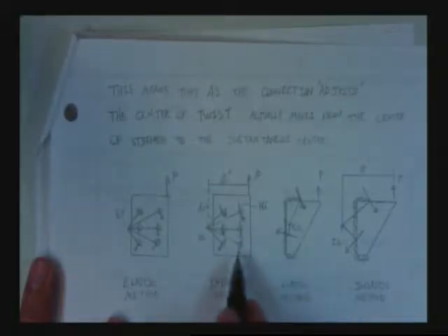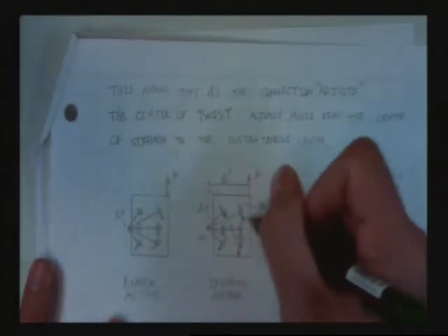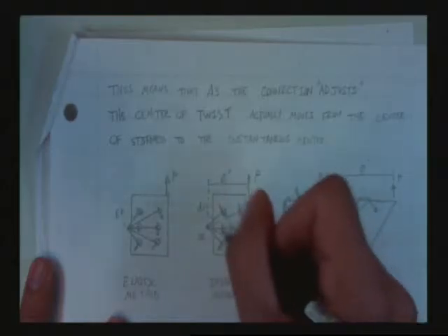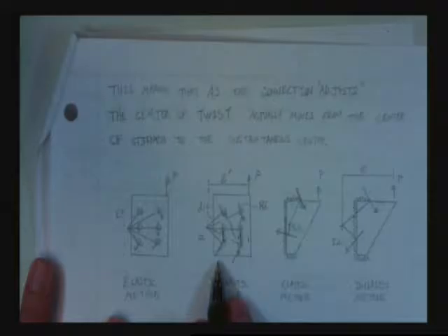We'll talk more about that coming up, but what you usually do is you'd say, okay, I see all these bolts going this direction. This bolt wants to go over here. This bolt wants to go over here. This bolt wants to go here. This one here. Which distance do I use for L sub C? Remember L sub C? You have to use L sub C to calculate if it's bearing or tearing. Which one do I use?